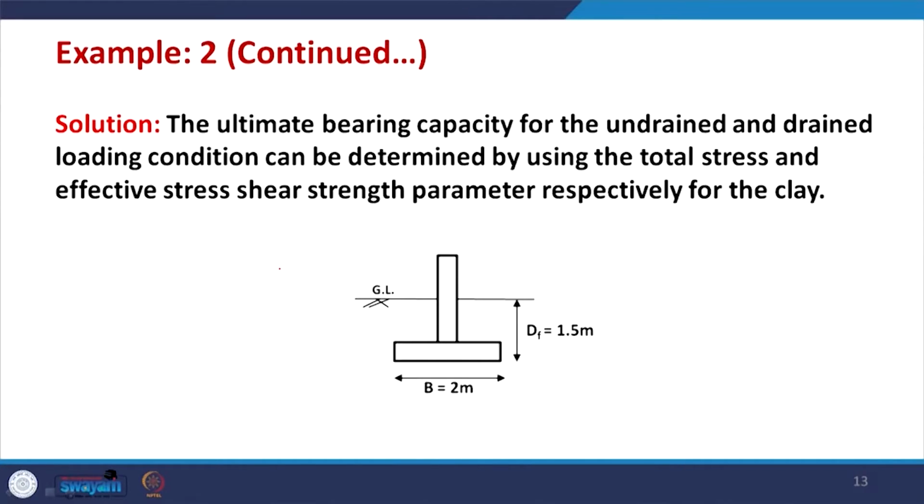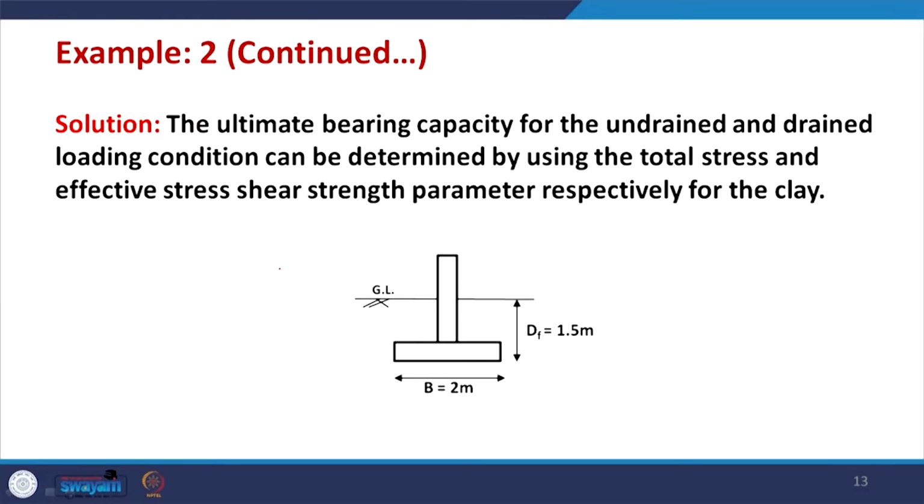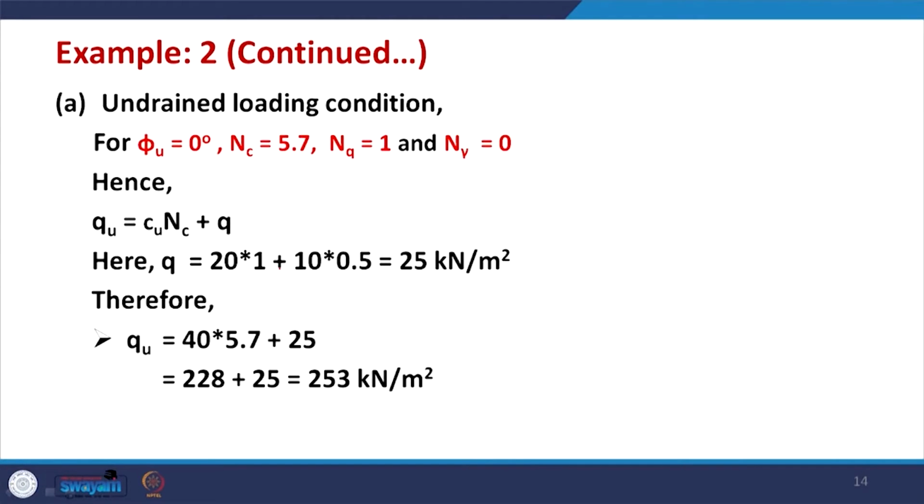Here the undrained and drained loading conditions can be handled using the total stress and effective stress shear strength parameters. So for the undrained loading condition we will use the total stress parameters, while for the drained condition you need to use the effective strength parameters.